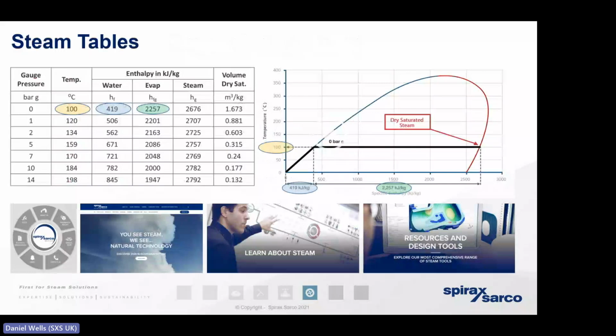Now, that's far, far less than the heat exchanger has been sized to expect. So as far as the condensate is concerned, when it exists at the process, at the heat exchanger, it's unwanted. It's a byproduct. We need to get that condensate away very, very quickly, because if we don't, that condensate is going to back up and flood the heating space.